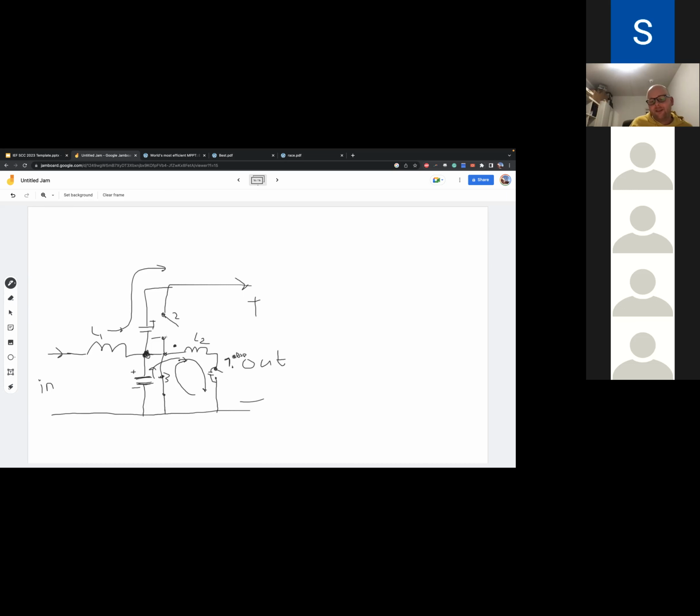And then all this energy that got released out of this bottom capacitor is stored in L2. And in order to release that, we need another diode here. So basically we try to move the energy from this parasitic capacitor to an extra inductor. We move energy from this capacitor to that inductor, then we turn on the switch, and then we move the energy from that inductor to the output again, to this capacitor here. I'm not sure if this makes any sense at all, but this is one way to get less switching loss and therefore higher efficiency at low currents.